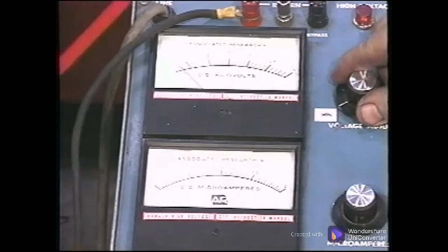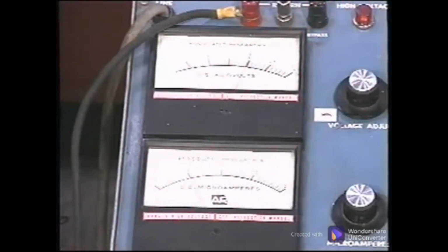acts as a capacitor. After the desired voltage is reached, in this case 9600 volts, it is held for a minute or so to determine if there is any current leakage. The unit should have linear leakage and no shorts after reaching this level. Each phase must be tested in the same manner.